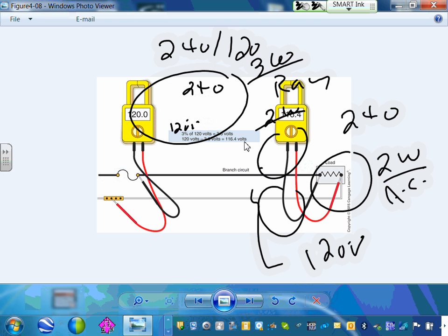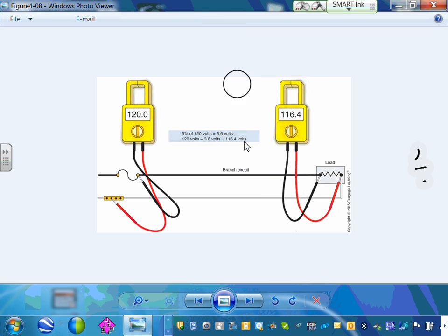Okay, we talked about the voltage drop, guys, and we'll do a voltage drop calculation. And we talked about the 3% and the whole calculation system here. Do you guys know, in terms of voltage drop, look at this, if we have a 3% voltage drop here, you start with 120. What's the voltage that you end up with here at the load? 116.